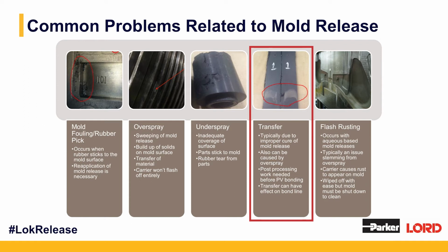to your parts. Other problems from transfer to the part are potential bond failure in knit lines in the elastomer. These problems can become a concern when mold release is excessive enough to transfer to the part. Cleaning the mold will be necessary and reapplication of the proper amount of mold release and allow enough time to cure at the appropriate temperature.